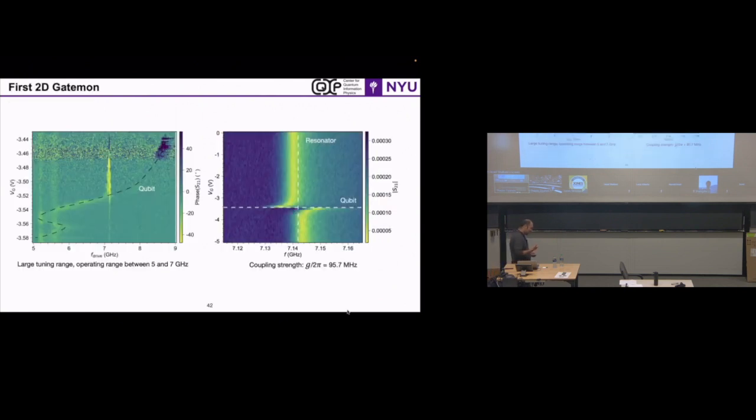So in our qubit, things are a little bit different. The way that we tune up our qubit is that we sweep the gate voltage as a function of frequency, because we have that capability, right? So we know that we can tune the frequency of the qubit. And the moment the qubit goes into a crossing with a resonator, we get an anti-crossing. So this is the resonator, this is the qubit. Then we know which one is qubit, which one is resonator, and we don't confuse ourselves.